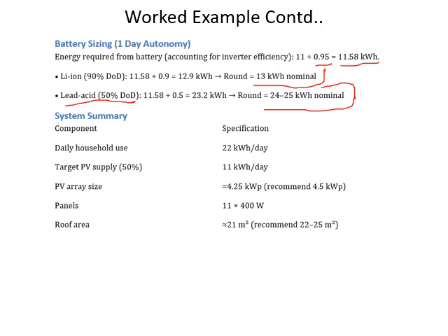Based on that you can find the kilowatt power. From the kilowatt power, depending on your selected capacity of PV panel, you can get how many panels you'll need. Now we have used the 400 watt PV panel each. If you are using 300 watt, then you will require a higher number of photovoltaic panels, right? Okay, so you'll need a higher area on your rooftop.